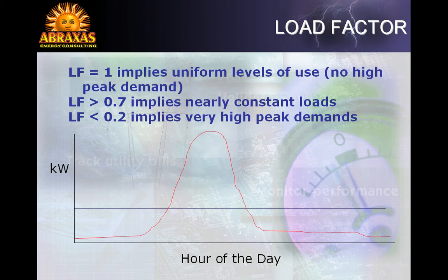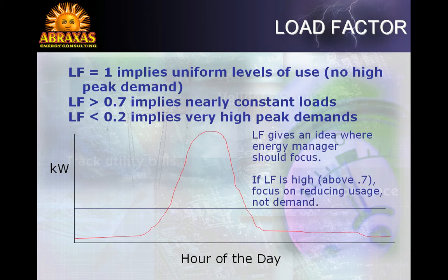Load factors less than 0.2 belong to meters that have very high peak power draws relative to the remainder of the sample. These meters could be associated with chillers or electric heating equipment that is turned off for much of the day. Low load factors can also be associated with buildings that shut off nearly all equipment during non-running hours, such as elementary schools. Load factors give us an idea of where energy managers should focus their efforts.